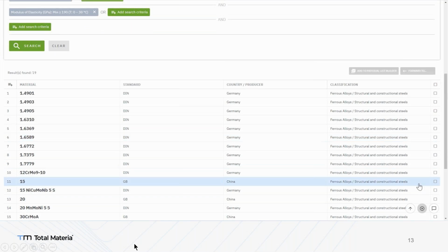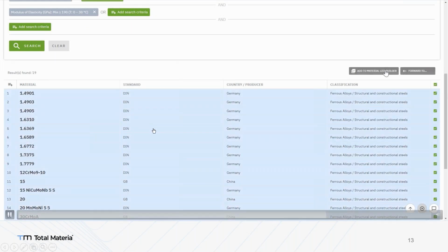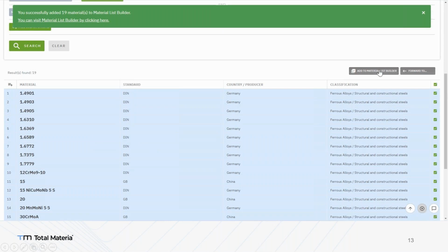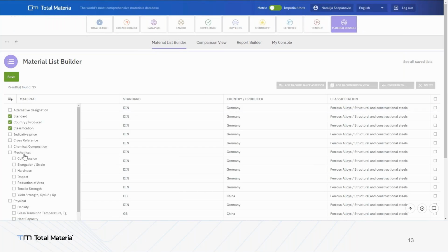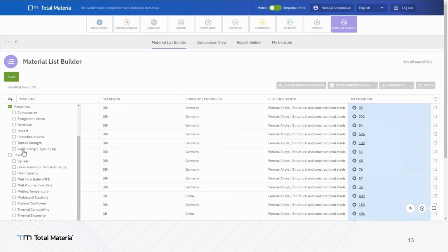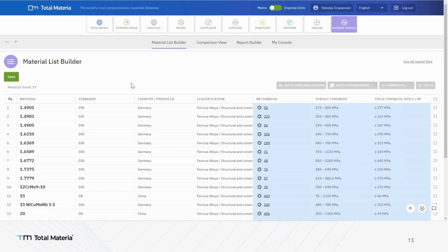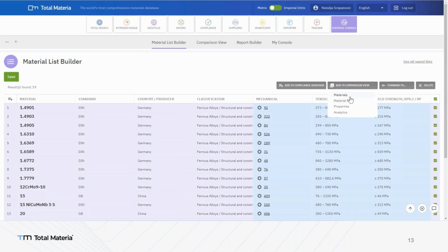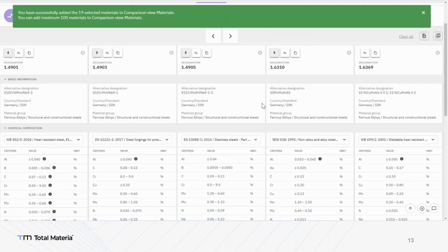So I'm looking for some material. We had 500 thousands of options. Now we have only 19 materials that can give me this. And then on GB standards, with this durability, with this resistance, these are the stronger materials. But still, I can compare these materials. Which one of those materials has the highest tensile or yield strength, or which one of those has stress strain curves, fatigue, and so much information. Which one of these materials has more supplier information, let's say, for me to find and purchase for the design.